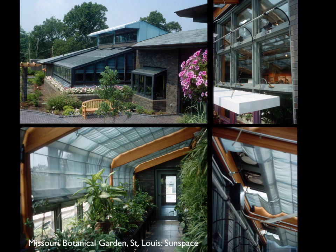So if the sun space is really warm, the space behind it is too cool, you can open those windows and let the warm air flow over into the space. When it gets warm enough, you can cut them down. On the lower right, you can see some little exhaust fans. So one of the things that happens in the summertime is the lower windows get opened. You can see that on the upper left slide and on the lower left slide also.